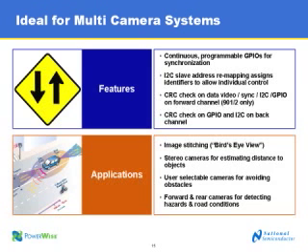Okay, so walking through the features, as we've said again and again, we have a continuous back channel, and programmable GPIOs are sent over this continuous channel to specifically support synchronization for multi-camera systems. The I2C slave address remapping, where we reassign the addresses for cameras, so common camera addresses can then be remapped, and individual control can be sent to each of the cameras. This also allows the side benefit of when repairs are needed, if there's some problem with the camera, a generic camera module can be added, and there's no need to worry about what the address is of that camera. They can all be common, and it's all handled with the programming of the deserializer.